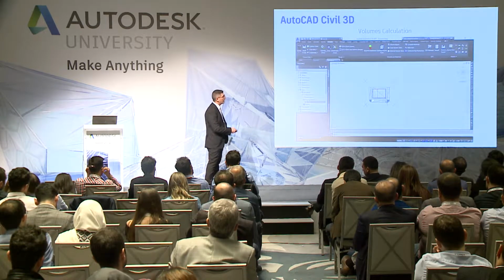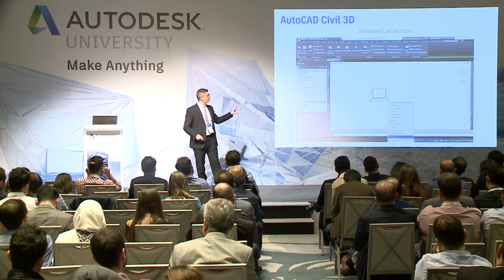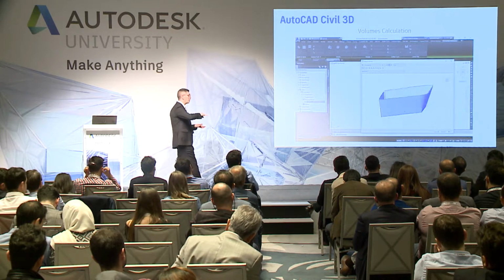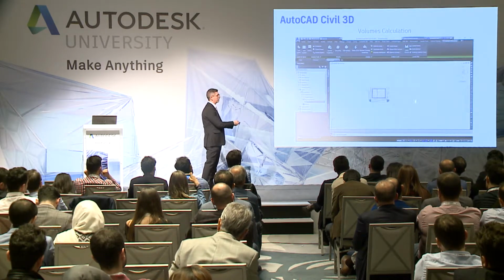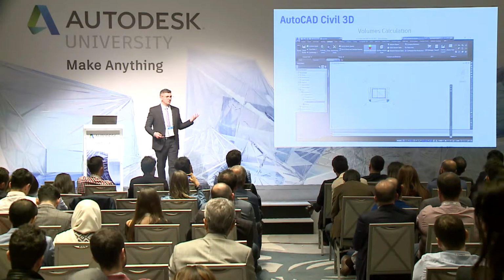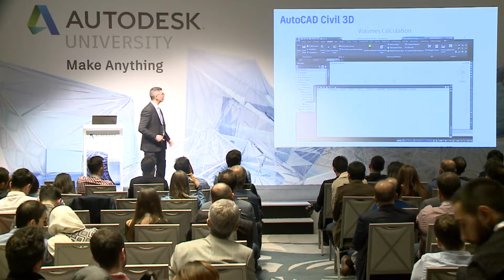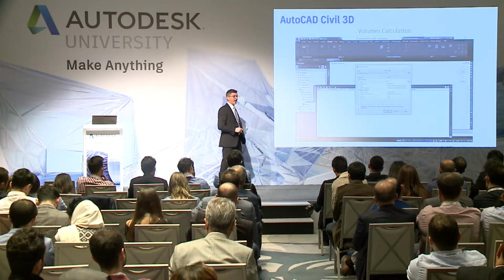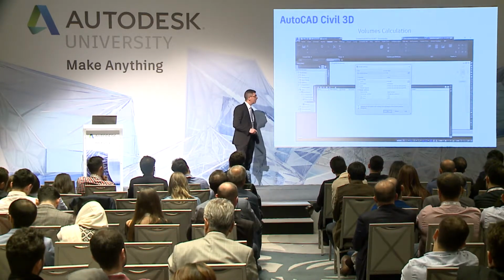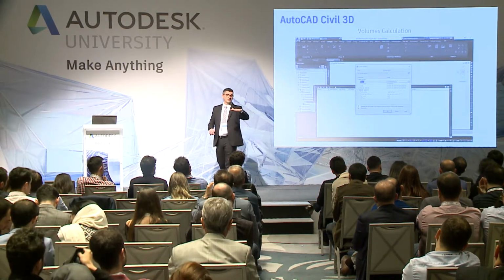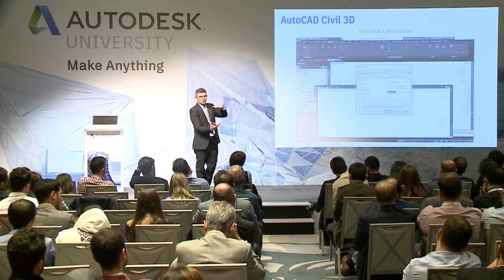And if you look here, the surface that I already created overlaps the previous one. It's like this one, OK? Why? Because for calculating, we need a thin surface. The thin surface allows me to manage the calculation. Then I can set the name of the calculation, and I need to set the base surface for the calculation, and the design surface.